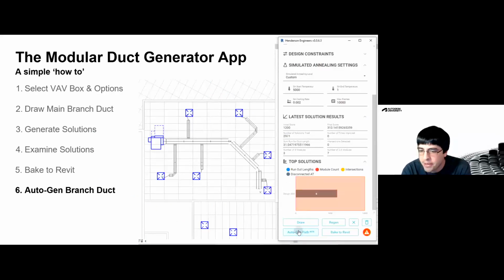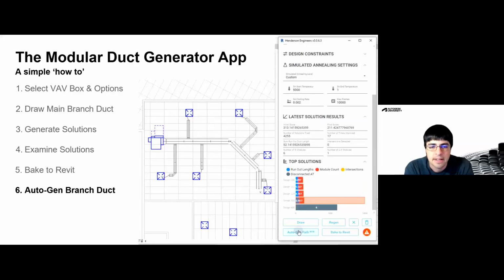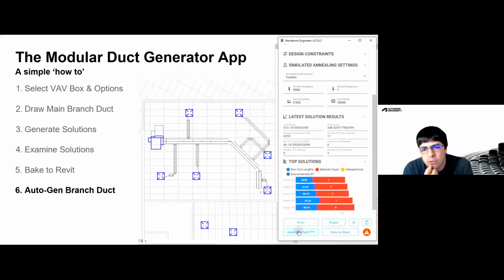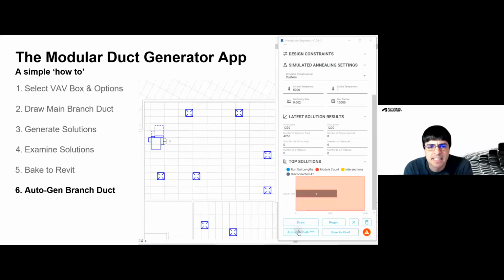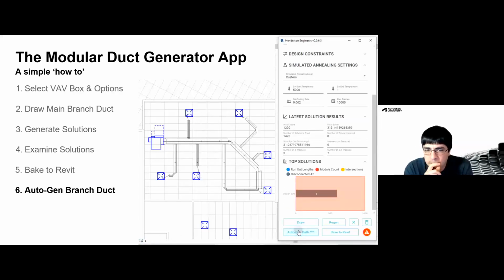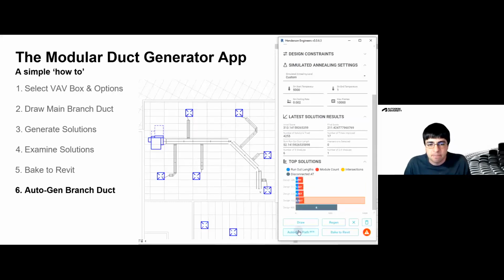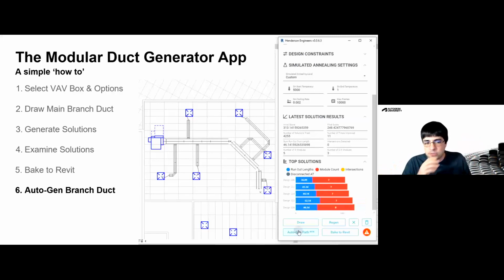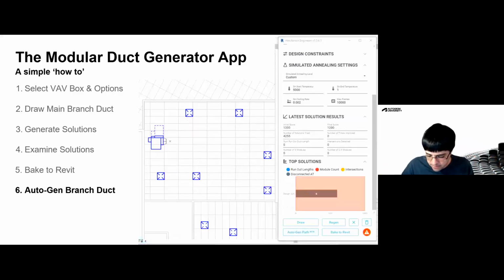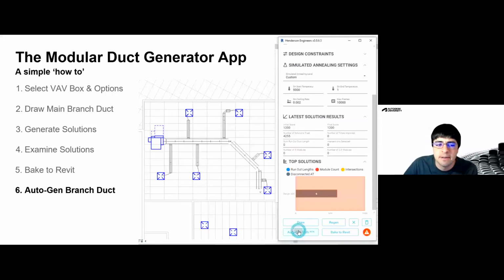So we have an auto gen button at the bottom. When you click it, instead of you drawing that main path, it'll draw it for you. Now, this is still in beta. I mention it because this was only like 12 weeks of developer time on this project. But you can see if we continue going, this might be the next step, improving this algorithm that generates the branch for it. Or maybe we move on to other things, like we'd start adjusting the air terminal positions to better distribute the airflow and shorten other runout ducts, or the VAV, or create the zones, which air terminals are in with all this stuff. This is kind of a preview of how we could expand it to that.